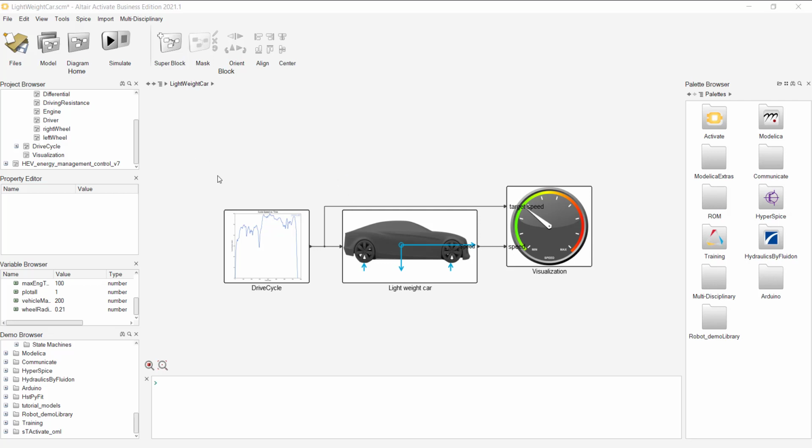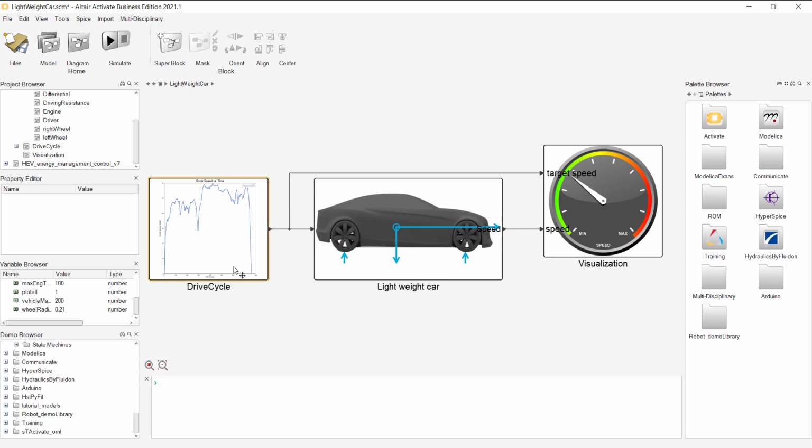And we have here a system model of a vehicle with input of a driving cycle. This is a speed versus time drive cycle that's going to command this vehicle to move while the vehicle experiences the dynamics that we saw in the slides before, the forces against it due to friction, braking, and drag force. And then for this vehicle, we're going to measure the energy consumption to follow this drive cycle while under the influence of these external forces.